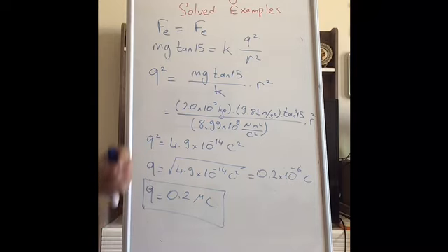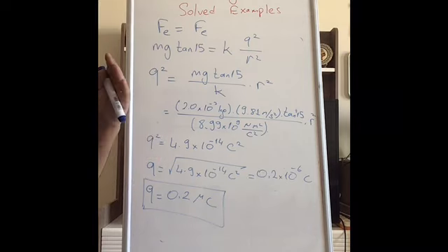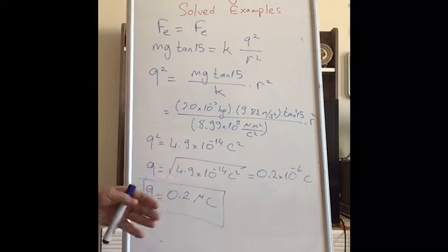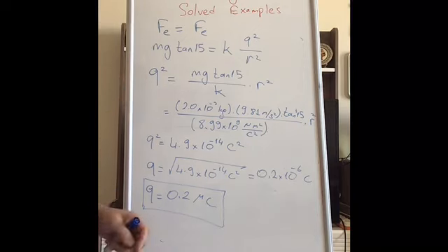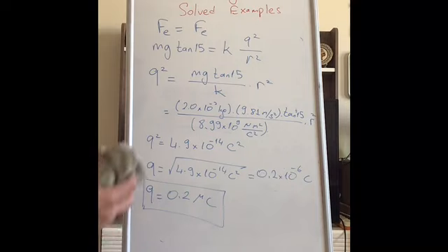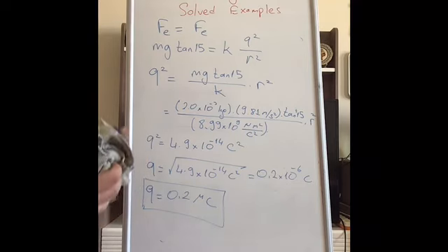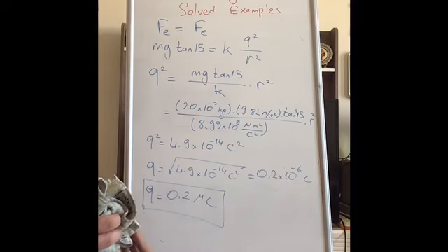It doesn't matter how simple the problem looks. First, draw the free body diagrams for each object in the system. Here we had 2 spheres, so we would have 2 free body diagrams. Then, since they are in static equilibrium, the net force acting on each sphere should be equal to 0. So we got the equations from the free body diagrams and then started solving.